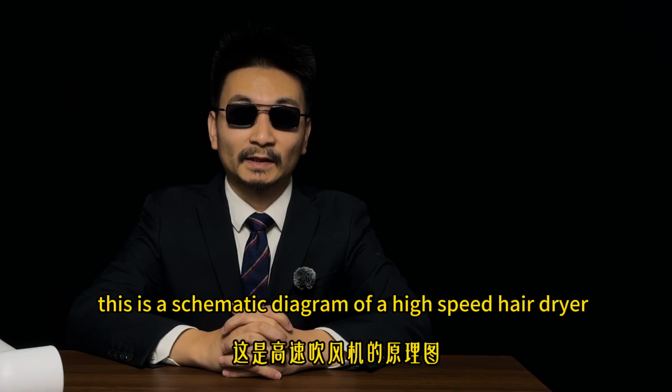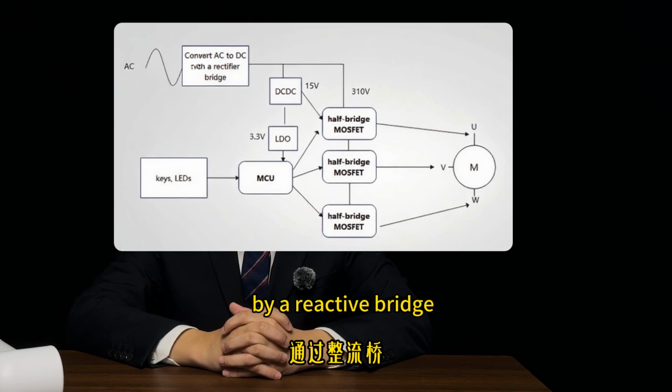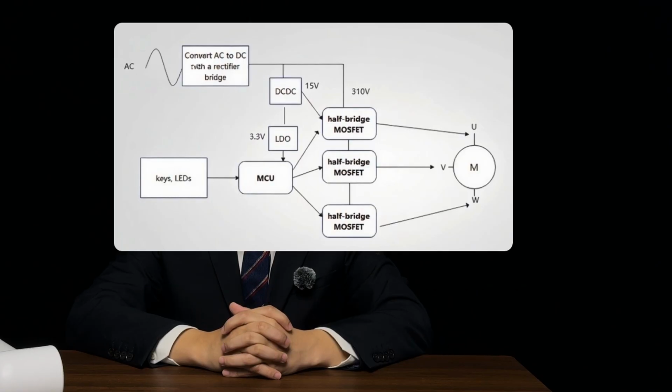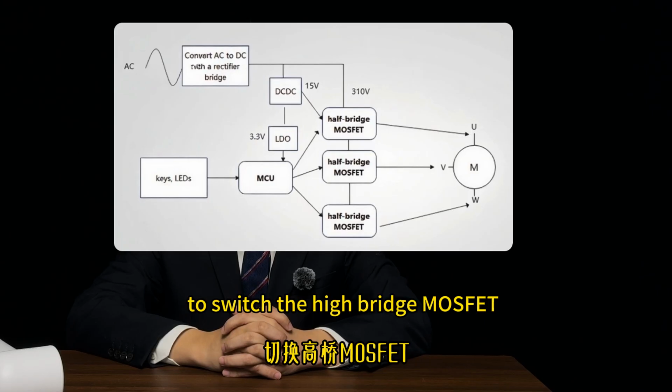This is a schematic diagram of a high-speed hair dryer. Alternating current is converted into high-voltage direct current by a rectifier bridge. On one path, the high-voltage DC is stepped down to around 15 volts via a DC to DC converter, which serves as the driving voltage for switching the half-bridge MOSFETs.